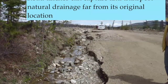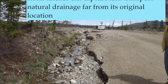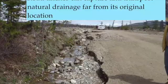If you have a lot of small drainages that are directed away from their natural course, and you have ditch lines that intercept and redirect surface and subsurface flow, these issues, not ECA per se, have caused the negative hydrological impact. So when you think about ECAs, you really shouldn't be thinking about the area that is harvested. You should be thinking about what kind of job you did on your road systems. That is the most important thing when we are thinking about impacting water quality and change to timing of flow in a given area.